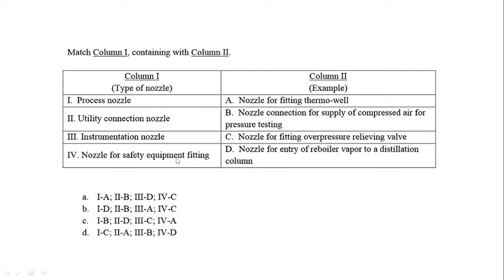So can you tell what will be the answer? Which one will be better, thermocouple or RTD? Actually, here both statements are true. A thermocouple is used for measuring high and low temperatures, and RTD gives a linear response. But the stability and accuracy are more in the case of RTD.